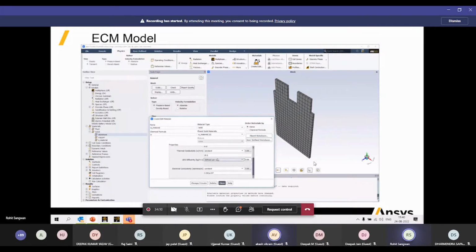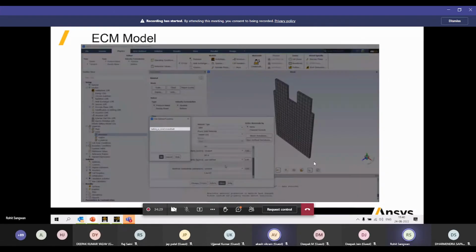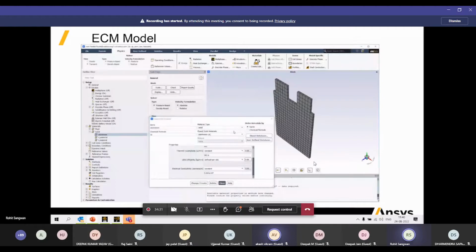For the active material, the electric conductivity is not used. For positive and negative tabs, I'll create a material by modifying copper that I've copied from the Fluent Materials database. The tab zone is passive, and the UDS diffusivity for the tab material must be defined through this user-defined function provided by Ansys Fluent. For passive materials, I also need to specify electrical conductivity.